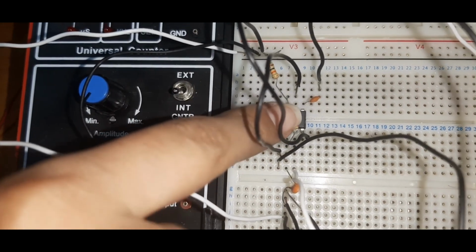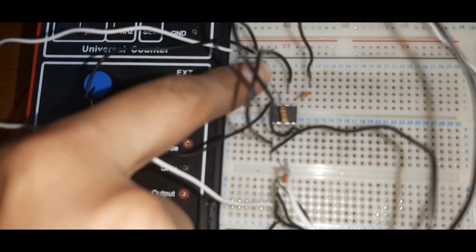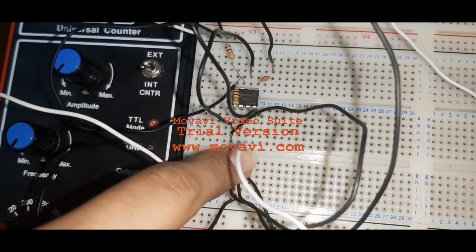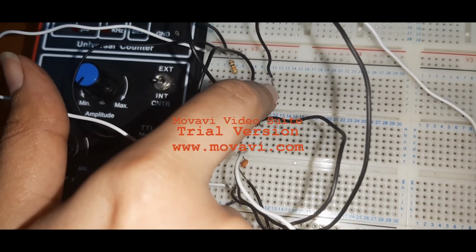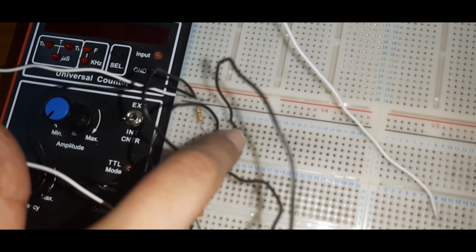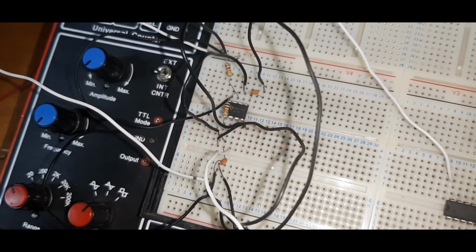These two resistors are producing the values of the duty cycle of the square wave, and this capacitor is producing the frequency of the oscillation, and this capacitor is used to smooth the output waveform. If I didn't connect this capacitor, then there will be ripple in the output waveform, that is a square wave.